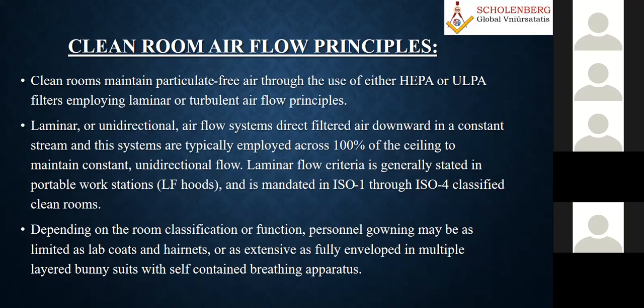So, having understood the definition and how it started, the history, generally in a clean room, as I told you, the air has to pass through various filtration levels, and ultimately you have final HEPA filters or alpha filters, and then there are standards for all these classifications. For the majority of the flow we maintain a unidirectional, laminar flow, which I also showed in some figures when discussing hospital air conditioning, where the HEPA filters are kept not at the AHU level but at the terminal.